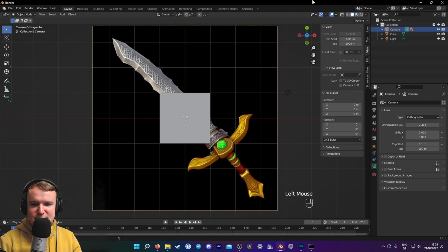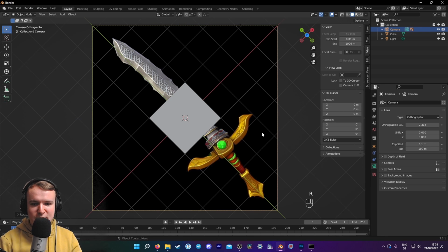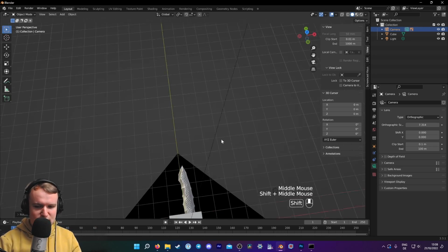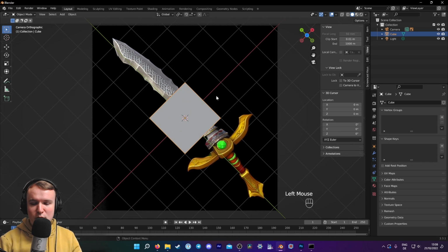Now what that does is it attaches the reference image to my camera. If I rotate the camera, the reference image joins us, which will become important in the next step because we're going to be rotating by 45 degrees. So R Z minus 45. And now you can see it lines up, right? The reason we made it diagonally originally is just to get as much detail as we can. And now we don't want to just rotate our object all willy-nilly in the Blender world. So this is a healthy general setup, right? And there we go. Now we're ready to work.